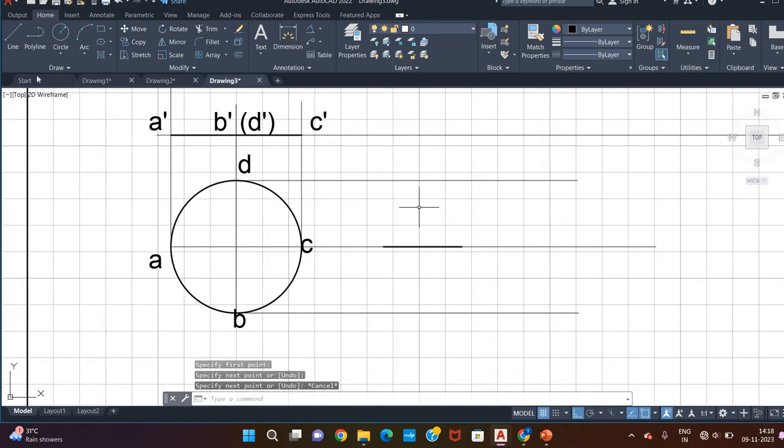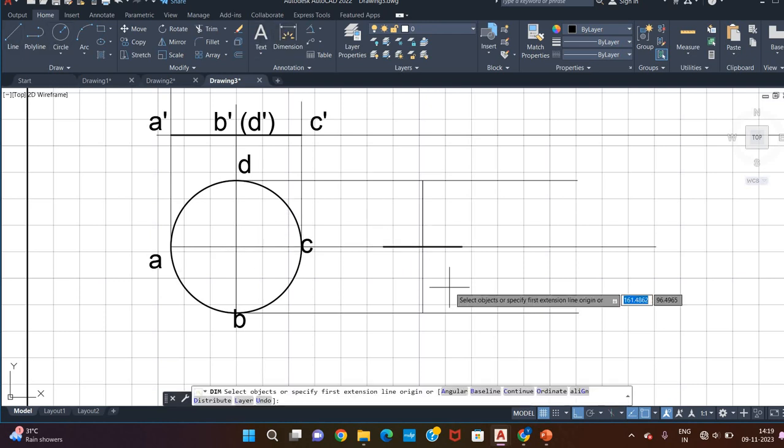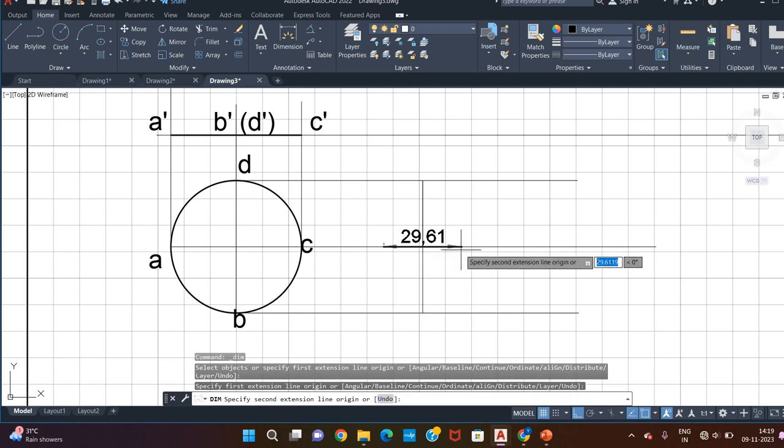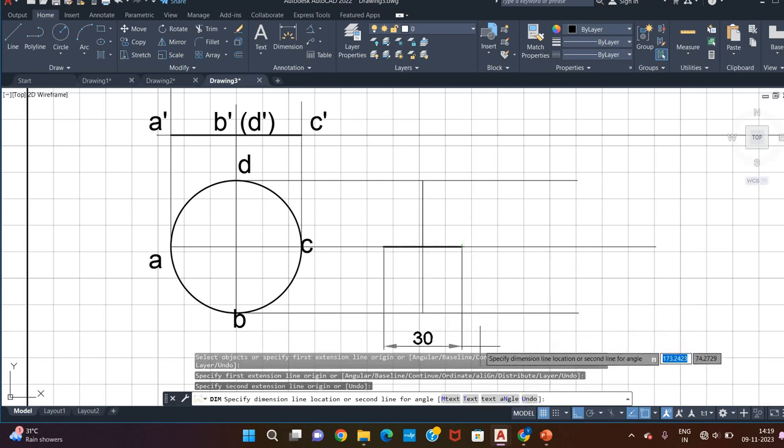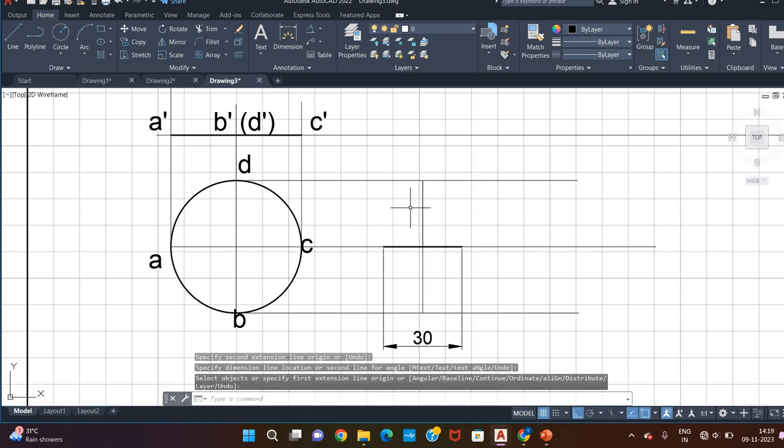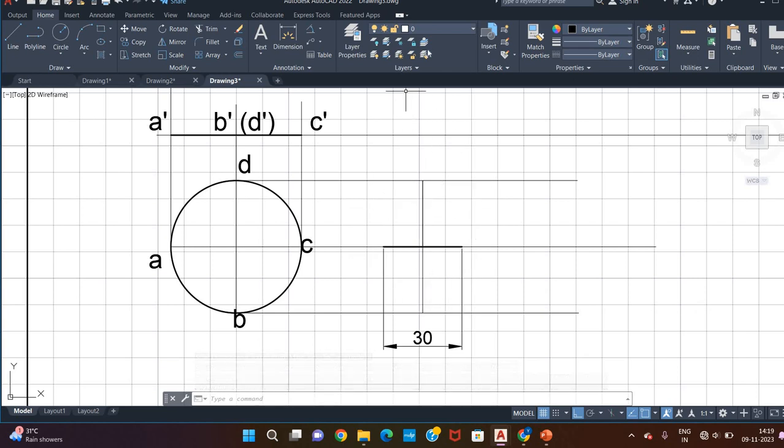We have projected all the points. This will be my major axis, in the middle. That axis will not shrink, but this axis will, that AC line. This axis corresponds to the AC line. So that is being set to 30 mm now. Right. So now I have to draw the ellipse by taking these 4 points into consideration.